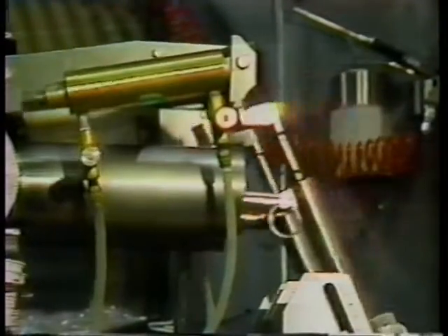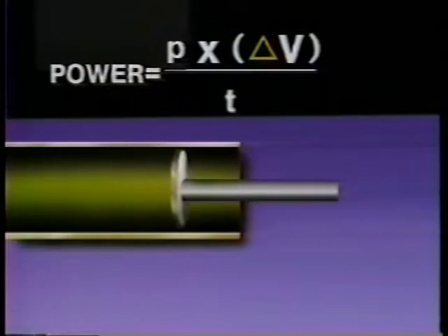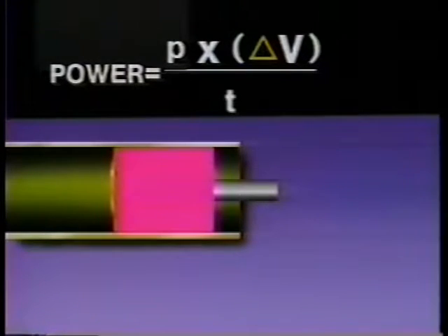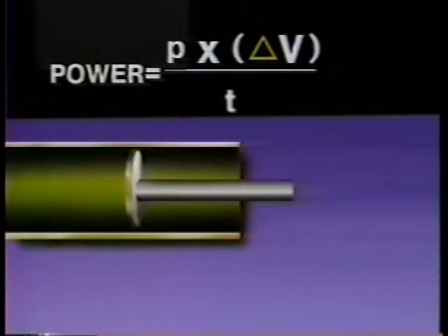We have also seen the second way of doing fluid work, when a constant pressure displaces a volume of fluid, such as a piston pump. To turn that work into power, we divide it by time, or measure how quickly or slowly the piston does the work of displacing the fluid in the system.